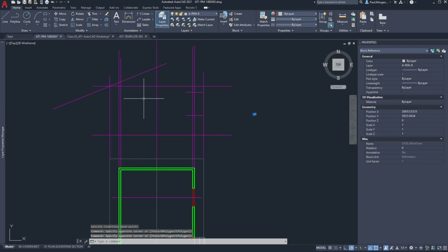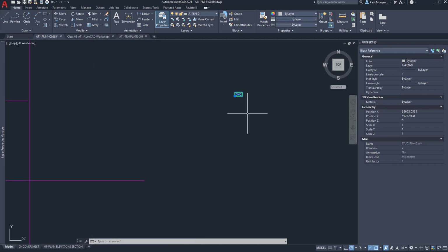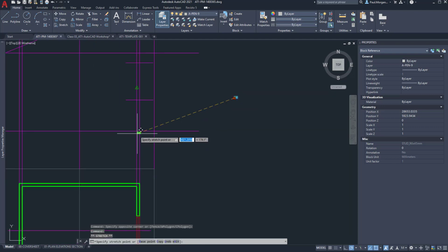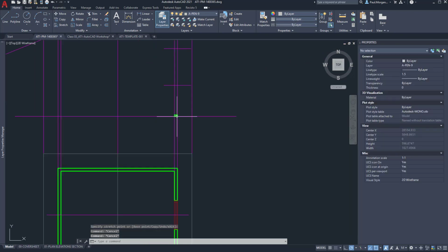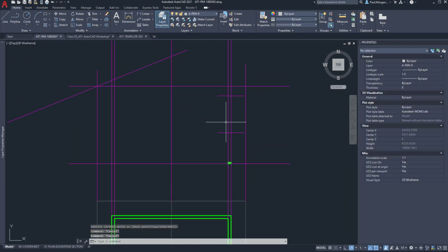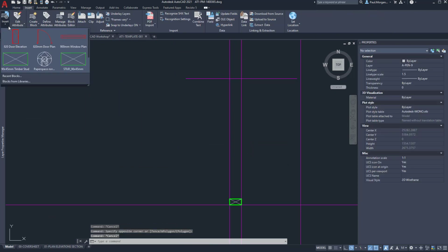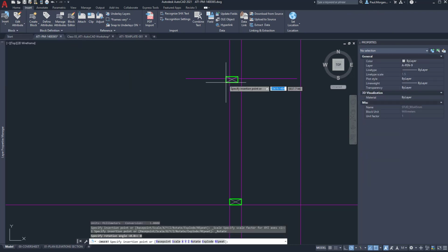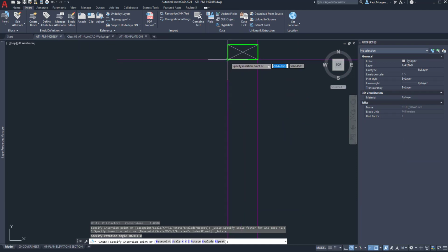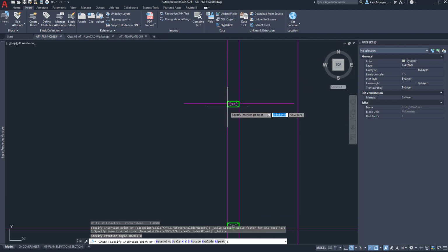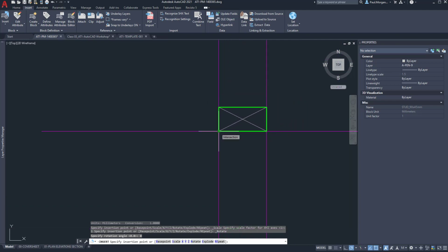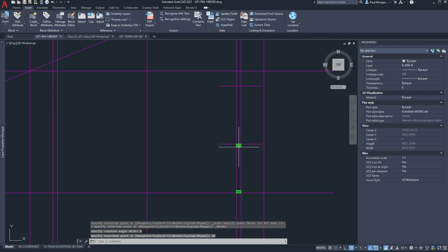Now, even as this currently stands, we can start to get an idea of how this is going to look. I'll show you. So I'm going to move this stud in between that there. Okay, we know that's our window, so I'm going to start copying this, or I could even use the insert tool. I can go insert, insert, and there's my block, there's my stud, and I can move this around. This is not going to work perfectly though, because the base point is below the corner, not above, and in this instance there's a stud just below the sill. But what I can do is I can just hover my mouse over this area and then start to move my mouse down. I haven't clicked on anything, but just type in 45, hit enter, and I know that now sits in the right area.